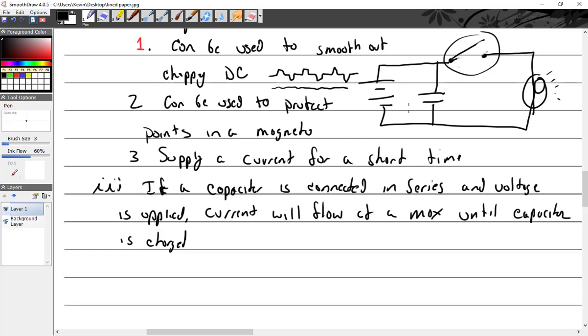So just like with this battery, if I took somebody else's ammeter and I go across these terminals, how much amperage do I get? All of it, right? Even though there's really not a lot of voltage, I get this massive amount of current. Anybody care to guess how much current I get out of this battery? You should know. 300 amps. Somewhere around 300. Pulse hot cranking amps is 460. Which should be a clue to those of you who tell me on your project that you just got 3,000 amps of current draw. Probably not.